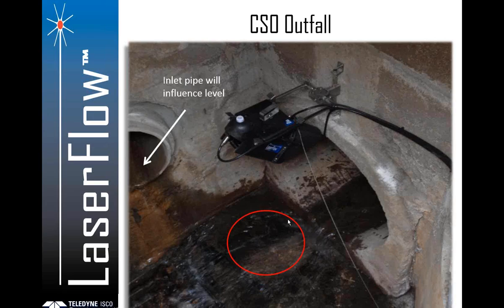So this picture is showing the remote ultrasonic level, and let me see if I can grab my pointer here and draw that. So this shows it cabled right here, and there's a band up into this pipe further there where that sensor is installed. So again, what would have been a previously difficult to measure situation, with the remote ultrasonic sensor, it makes that much easier.